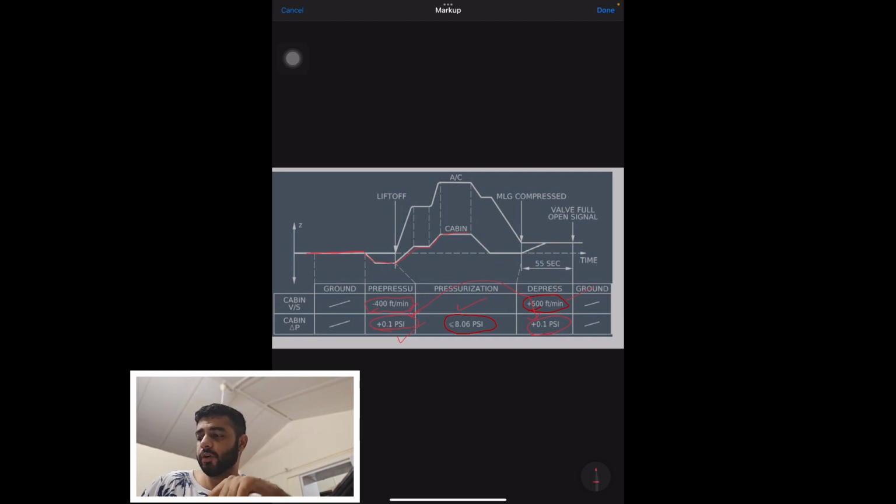And in manual mode, finally, manual mode is where you will press the manual push button, and then with the VS you'll be able to select the outflow valve, closed or open. Now remember the outflow valve is like this. When I put it up, man VS up, this is basically opening up, so air is able to come out. And in case I put it down, then the valve closes.